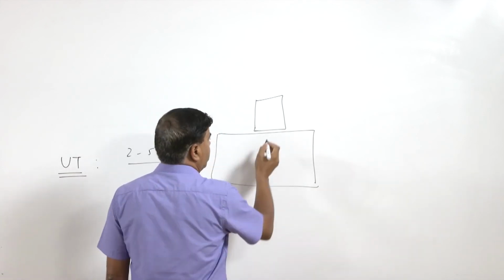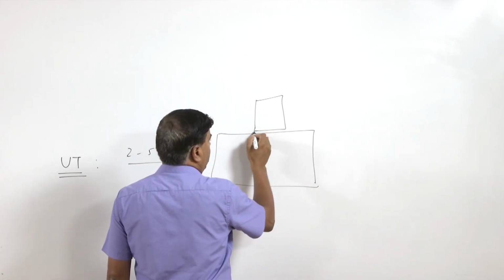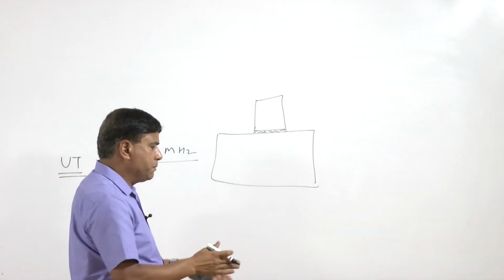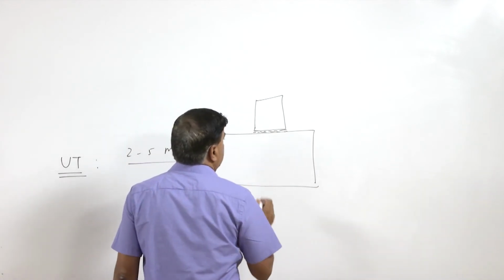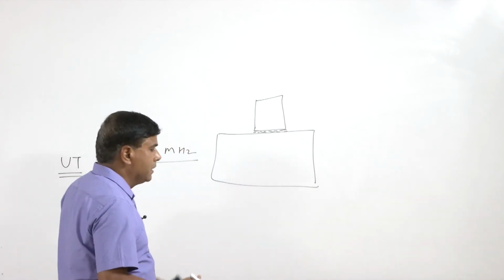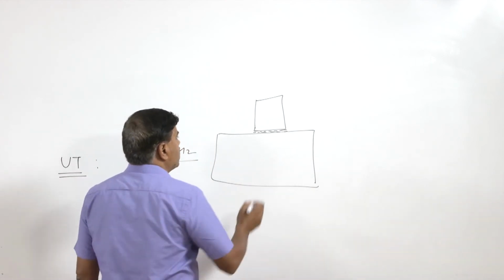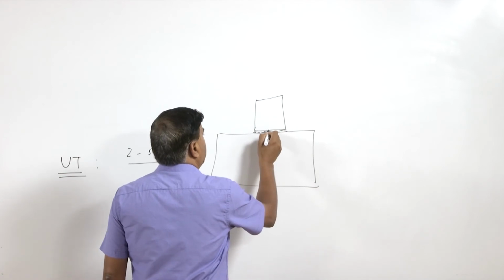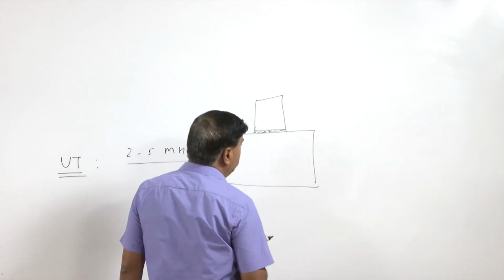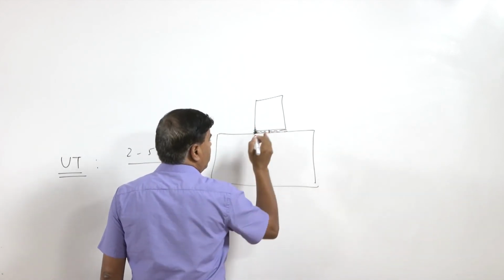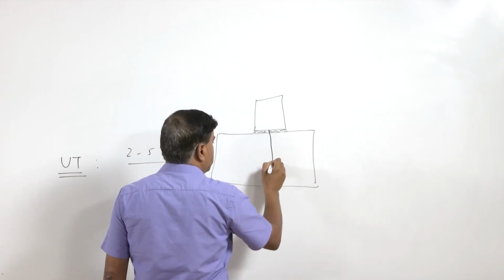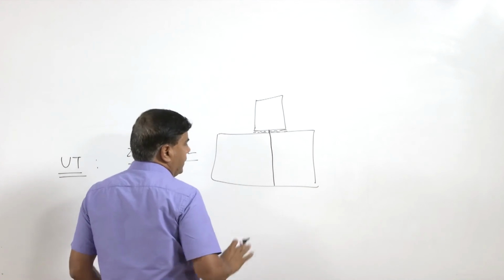The principle is simple: between the source and the component we use a coupler so that it can transmit the vibrations into the component. So, whenever there is a change of medium in the path, the waves are reflected back. When the vibrations are directed onto the component, they will be reflected back first from this surface, and then a part will be transmitted through the thickness.